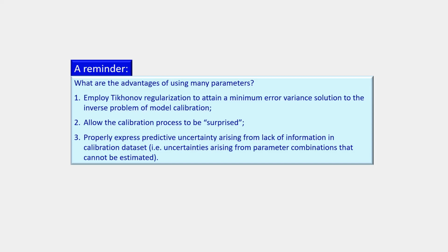We find out a little bit about what's under the ground through history matching. And by having parameters at all parts of the model domain lying in wait to receive information about what may be under the ground, any heterogeneity that requires expression can be expressed by the appropriate pilot points.